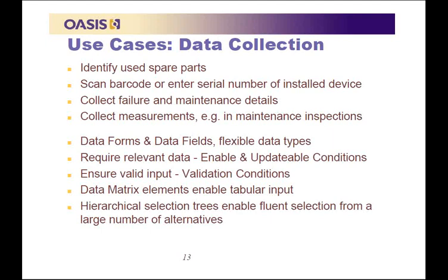For example, the failed component or components are to be identified and the occurred failure mode and failure mechanisms recorded if known. In the case of the oil and gas industry, standards define extensive information to be recorded for maintenance activities. Similar but less detailed requirements exist in service business related to heavy machinery. Some fieldwork, such as overhauls or maintenance inspections, includes measurements. Results are to be recorded in the context of the equipment or component in question.